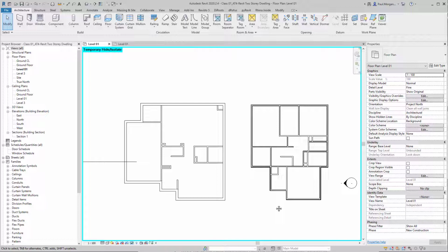We could have just drawn level 1 straight over the ground floor. And there's absolutely nothing wrong with that. And generally when we're designing buildings, or if we don't have a reference set of floor plans, that is exactly what we would do. Again, the only reason why we drew them off to the right and then we're going to move them across is because we had those floor plans there to reference, so it made sense to continue using them. But nonetheless, you always need some sort of anchor point or reference point between the two levels.